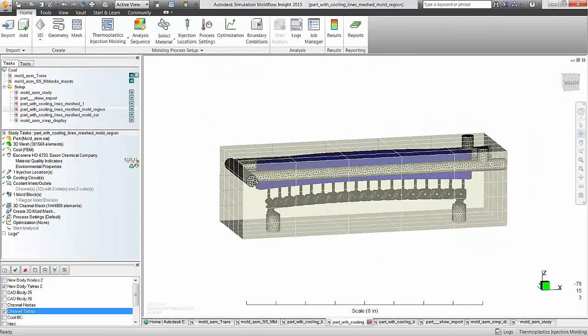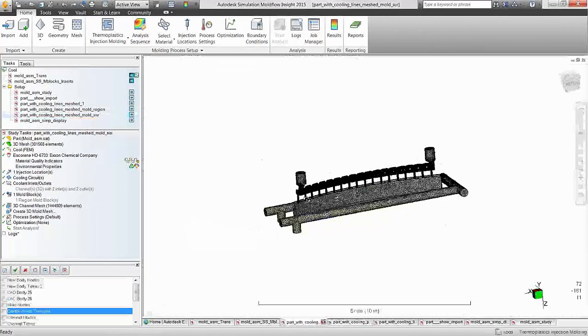So yes, if you've done FEM, you can literally not bring in mold blocks, right? Tag the mold blocks, tag the inserts, which I'll show in a second. You can just take an envelope approach, mesh that internal and external, and then convert it to a 3D block. So one piece of steel. That's a very quick setup. So maybe we don't have all the details of inserts, components that are in the mold.